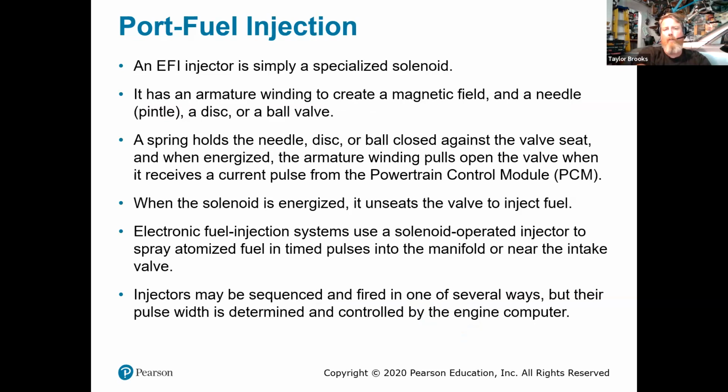Now, we will have the fuel injector operate a little bit differently, typically. We're going to have it act more as a solenoid in this case versus the throttle body injection. We're going to have that solenoid energize once the PCM gives the injector ground. It completes the circuit, opens the pintle off of the needle, and that is going to spray fuel in.